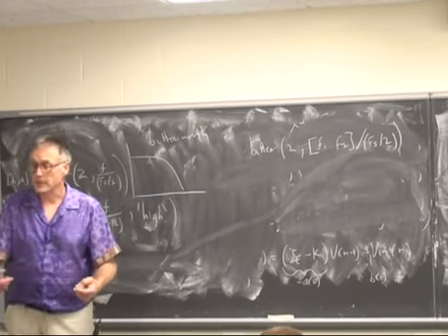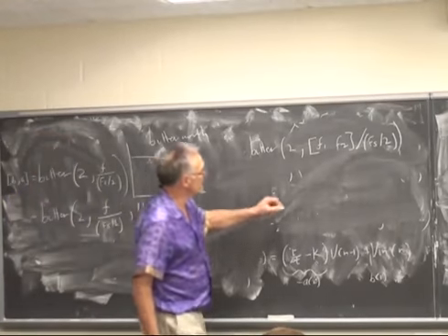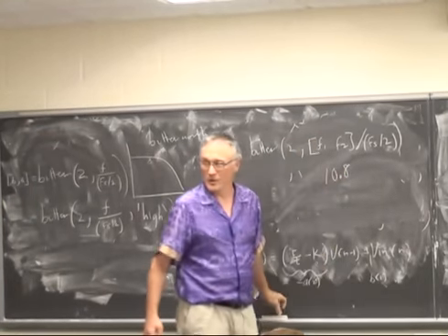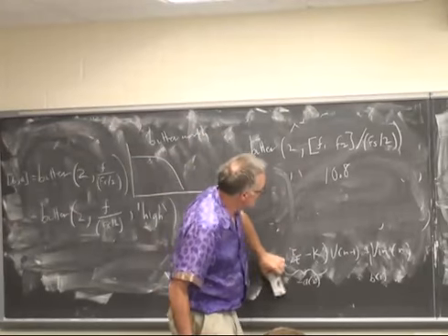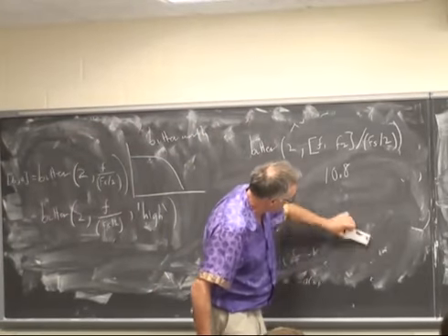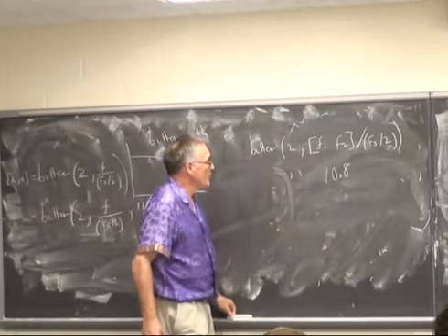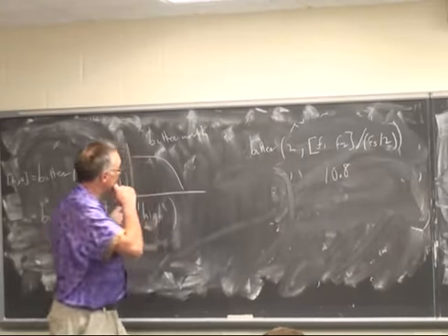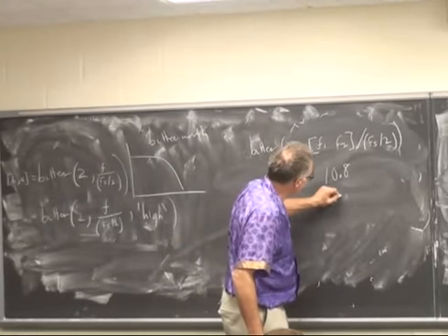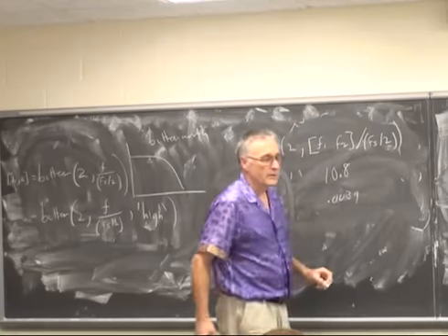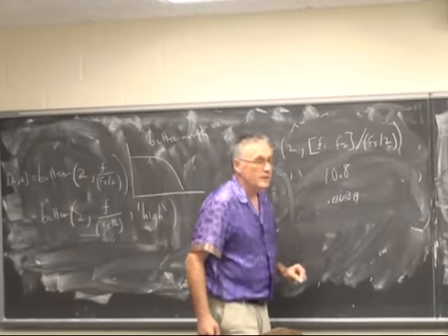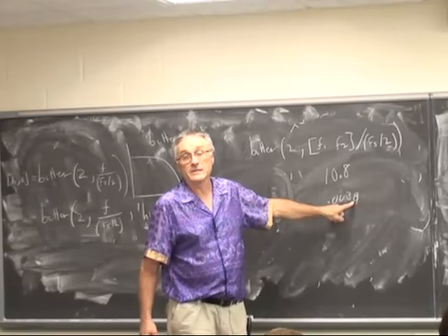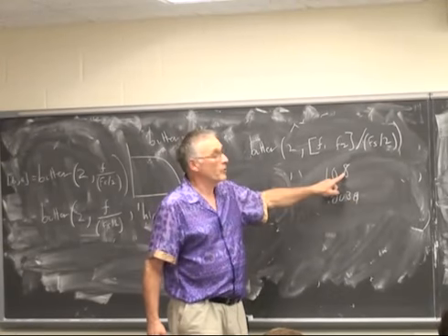If you evaluate, let's say that you're using 10-8 format. Let's say you don't rework the multiplier, but just use the multiplier I gave you. If you use 10-8 format and you find that one element of B or A gets down to 0.003938, that will now evaluate to exactly 0 in fixed point format.